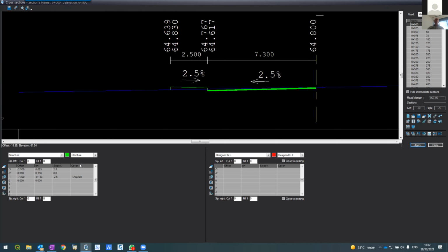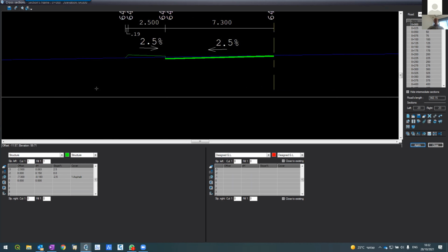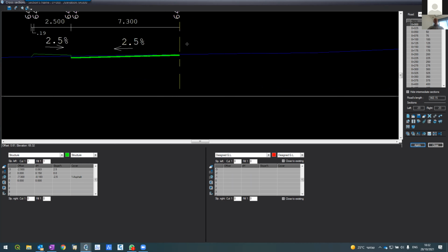I hope you can follow. And I want to end up here, because I do land development here, or you know what? Let's tell the software if you are cutting it 1 to 4 and filling it 1 to 1, like this. Fine. Let's now design the right side.